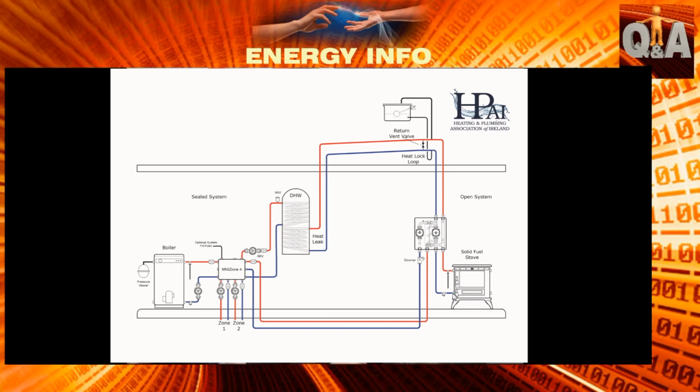So for gravity feeds, basically, what you're saying is that the cylinder always has to be higher than the bottom of the stove. If the cylinder isn't higher, it just can't work. Hot water wants to rise. It rises in cylinders when you turn on the immersion. So you have to allow for the natural occurrence that hot water is lighter, is less dense, it wants to rise. Yeah.